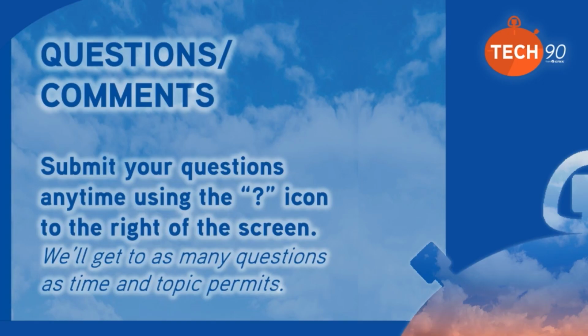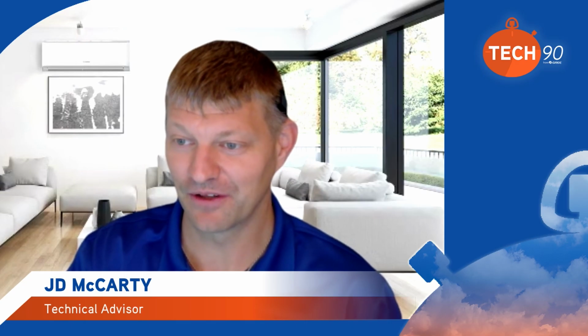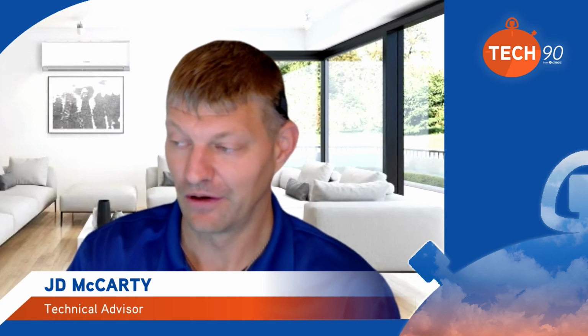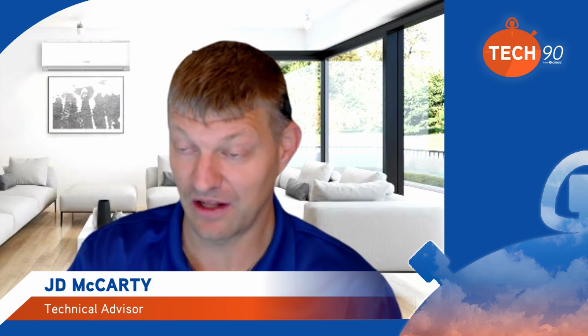All right. Any more questions, JD? No more questions, but just a comment from Steven. He said the quality of the copper might affect your flare, so that is a good point. Be sure to know where you're getting your copper from and get some good quality copper. Some of it can split if it's not quality copper, can split when you're trying to do your flares and flaring that pipe. So that's a good point to keep in mind.